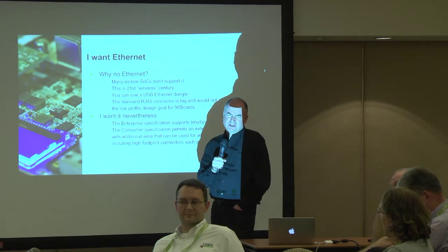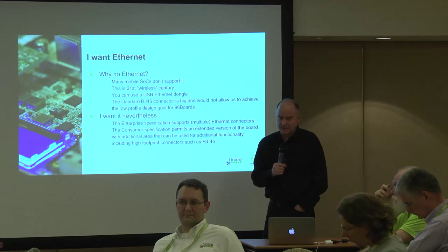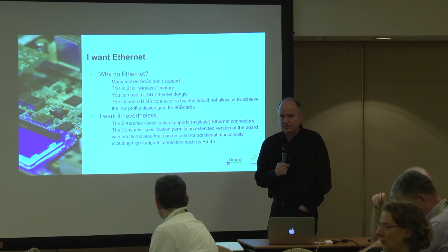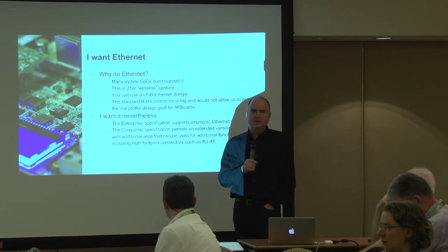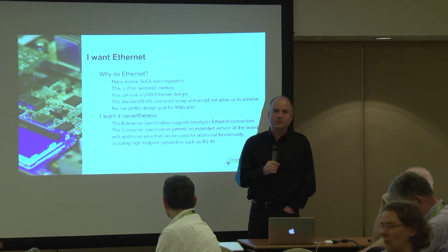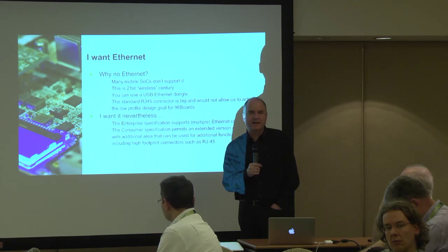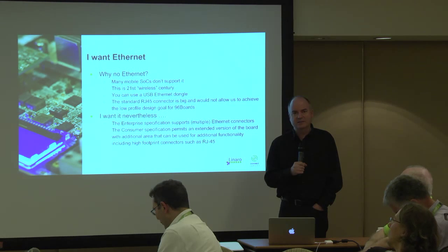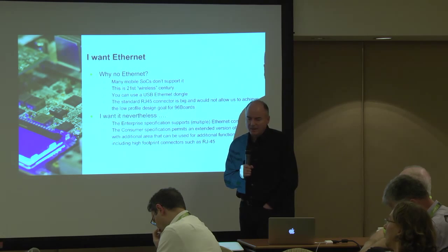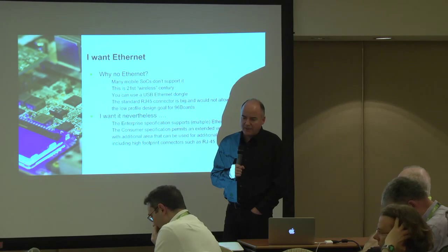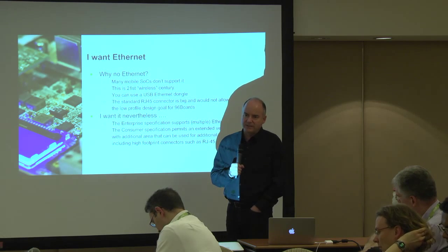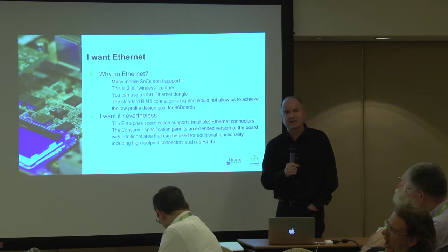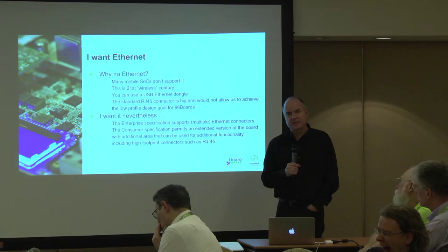Yeah, so there's a couple of things here, right? First is specifications like this are very difficult to change once you've got initial boards out there. So, for example, moving the connectors or changing the functionality of the connectors that are there is generally a really bad idea, because anybody who's started to work on the existing design is going to be messed up. However, things like adding mandatory features, for example, or adding a third connector for something, or saying you must have this in addition, could be added later.